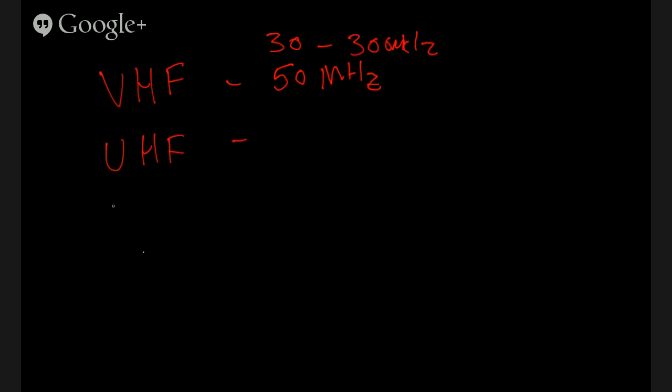So, question 1 in T3 is, should another operator report that your station's 2-meter signals were strong just a moment ago, but now are weak or distorted? Generally, the way you'd solve that issue is moving a few feet to the left or the right, because what can happen on VHF is something called multipath distortion, where you have your transceiver, or transmitter in this case, and it's broadcasting relatively omnidirectionally.